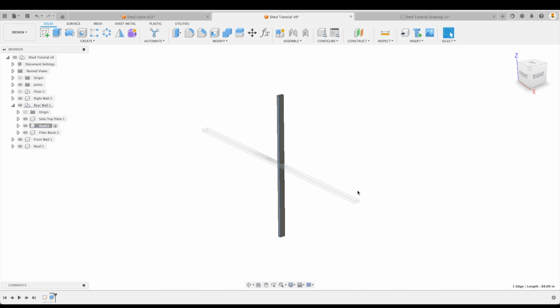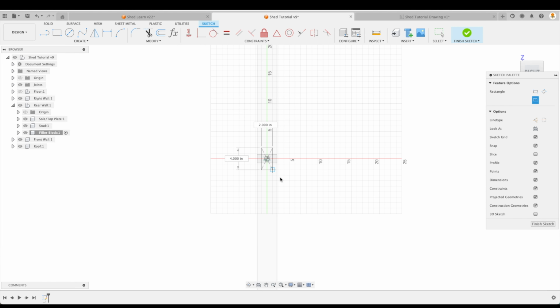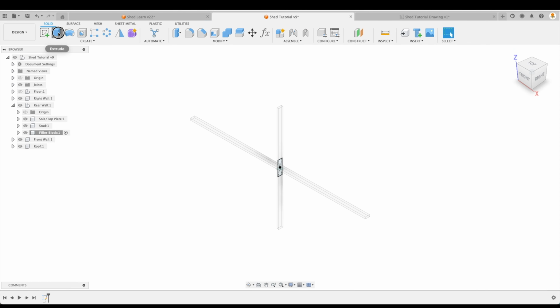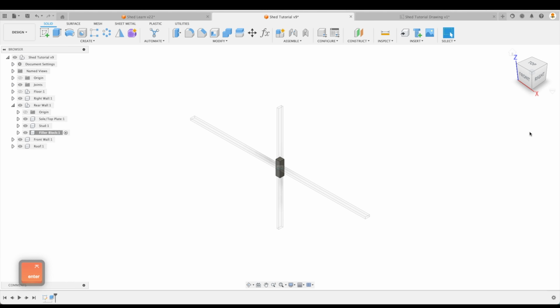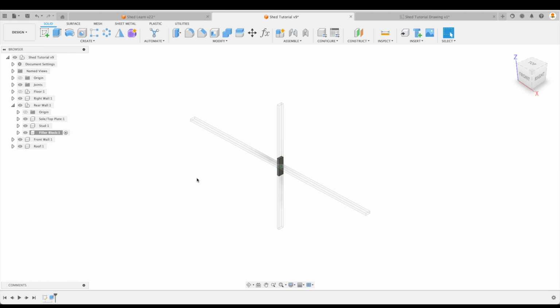So we're going to have the sole plate and 2 top plates. So what's this? Let me just do the math here. Yes, it is 88 inches spot on. So that's our stud. And then our filler blocks, let's just go there. And this guy we can create on the same plane. Go to our origin. This is going to be just 12 inches tall, 3.5. Perfect. And let's extrude that as well. Symmetric, whole length, distance 3.5. Oh, no, that's a little bit too much. We want to go 1.5. There we have it. So we only have 3 components for our whole back wall.